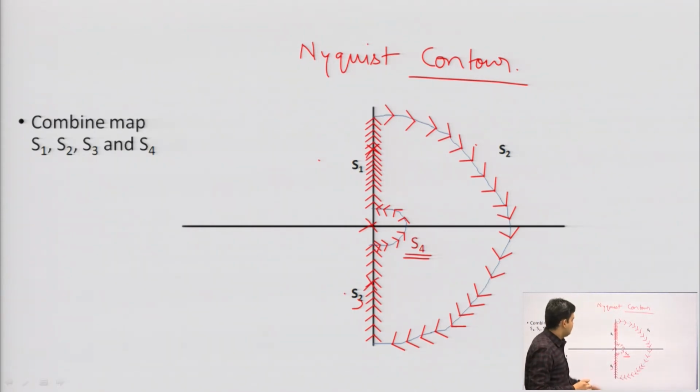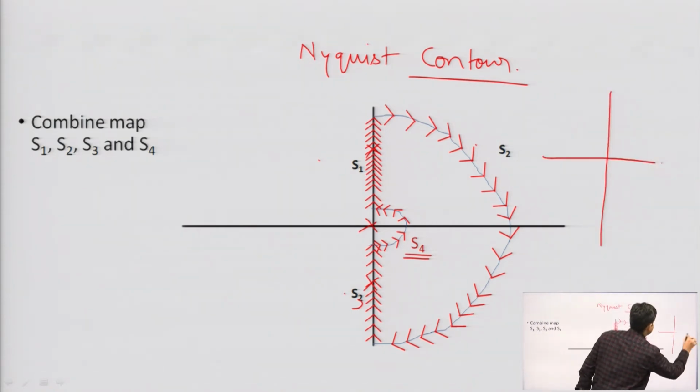Okay. So, in that case, what changes in the contour will come? In that case, I will assume my poles are lying on the imaginary axis, suppose some pole lying at the origin also, then my contour will move like this.